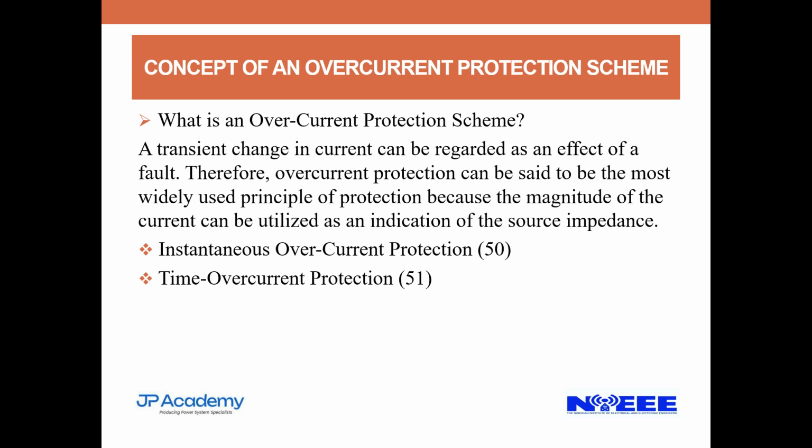Differential protection works based on the principle of Kirchhoff's current law. The sum of current leaving a node is equivalent to the sum of current entering the node. So it is usually employed on equipment such as transformers, bus bars, generators, and all that.